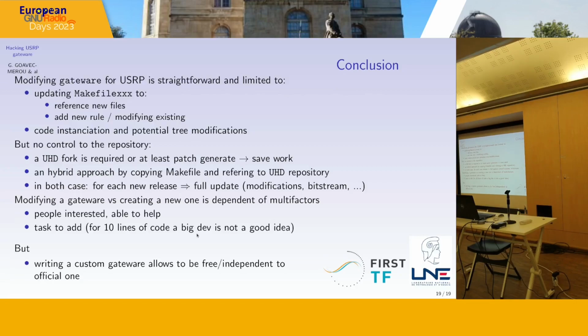In fact, I've simply used a switch to just shut down the input. That was part of the reason for corrupting the stream. If you do a correlation, and you don't know how long the correlation takes, it's not completely obvious. With a trivial FIR filter, it's easy enough to know how to calculate it, but with a correlation it's not.